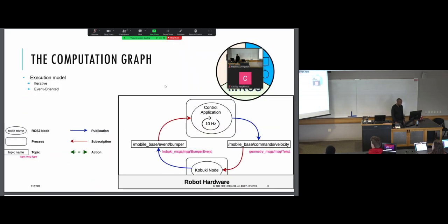Skipping over a lot of stuff here. This is very useful for algorithm development. Everything runs as nodes. It could be C++ or it could be Python. It has a main method, and they communicate with each other with topics. So that particular robot has a LiDAR, which is a scan topic. It has an IMU, which is an odometry topic there. And then you can add your own nodes for navigation, obstacle avoidance, pathfinding, and so on.